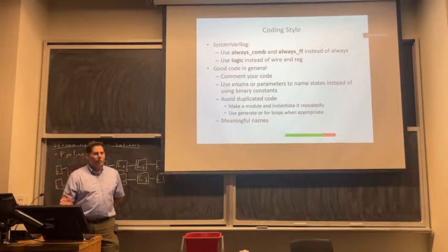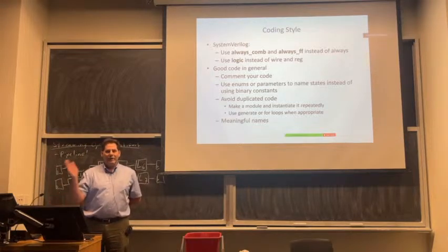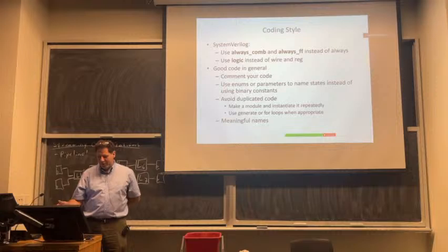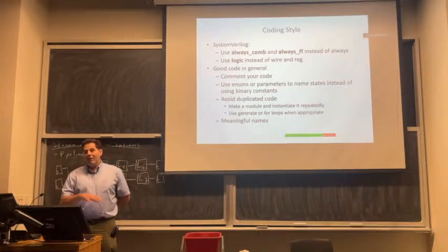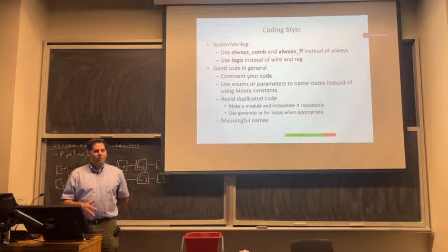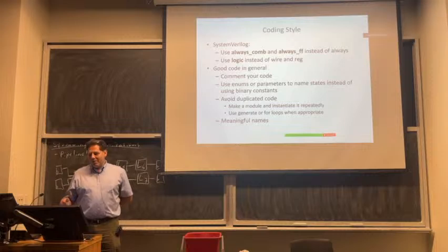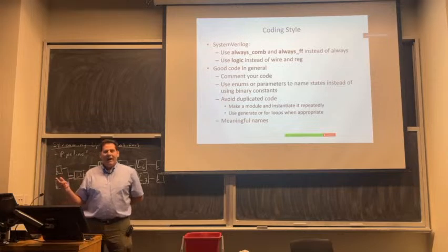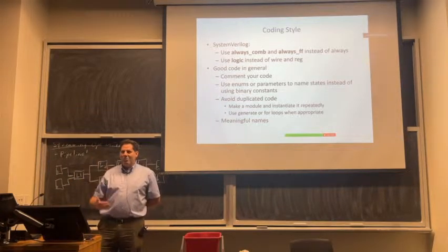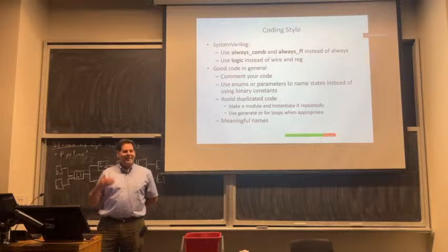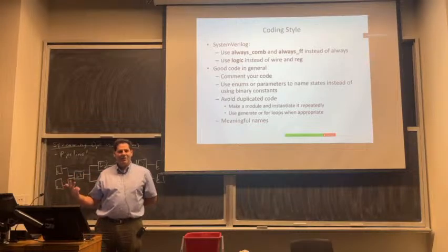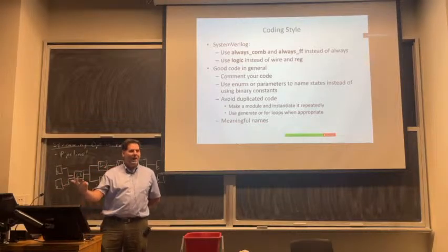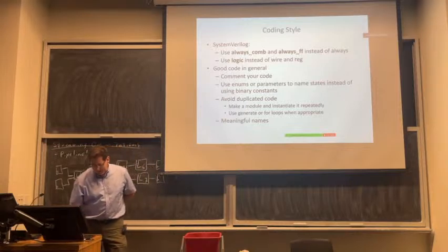And there's just rules you have to follow. You don't actually get to choose. In this case, you must use wire. In this case, you must use reg. In SystemVerilog, you can still use wire and reg. So if you're like, I memorized the rules, I love the rules, I'm going to use the rules to show I know them, you can keep using them. But if you never understood these rules, you found them annoying, you can just call everything logic, right? So all of your signals can just be logic, which is way smarter, because the fact that the rules give you no freedom is a good sign they shouldn't be in the language. You should just have one keyword, and the compiler should figure out what to do. So if you use logic, that's what happens.